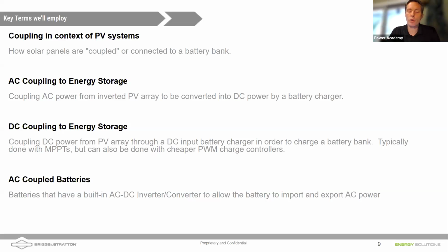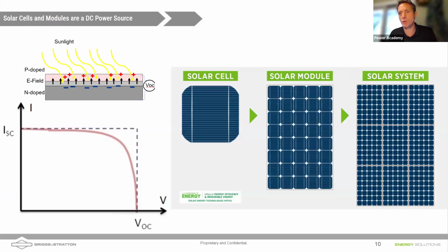Yeah, you get it overall. There are advantages to both, right? You mentioned how AC coupled solar arrays can do a little bit better with shading issues, and we're going to jump into that. But having a DC coupled system in full sun, you're going to be more energy efficient overall because you're not doing as much of the conversion process. Every time you take electricity and switch it from one type to another, inevitably you're going to generate some amount of heat, right? And the heat that comes from that conversion process, that's your energy loss.